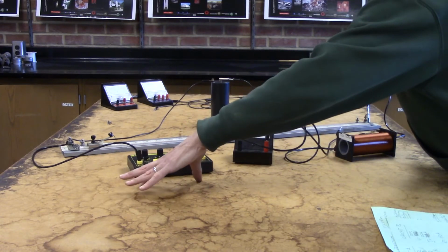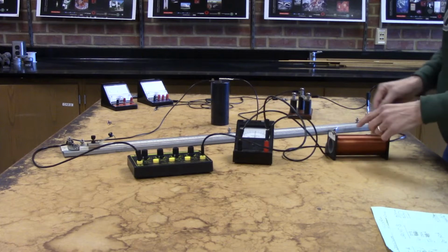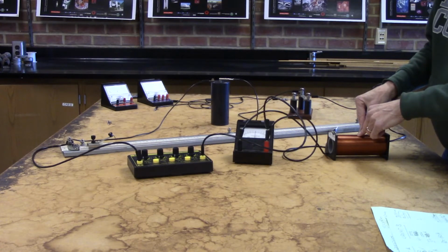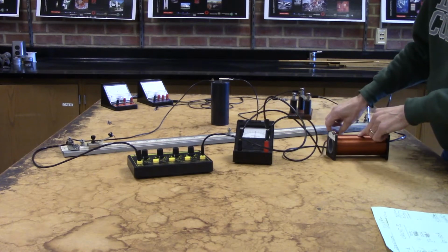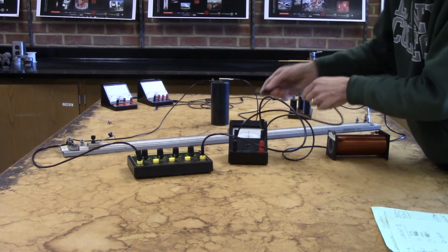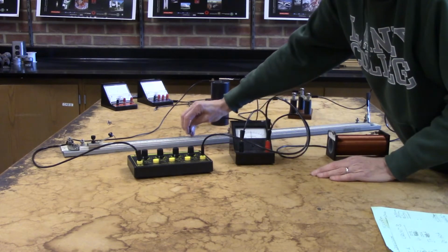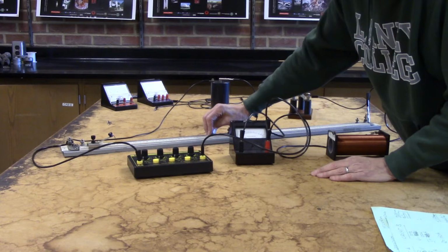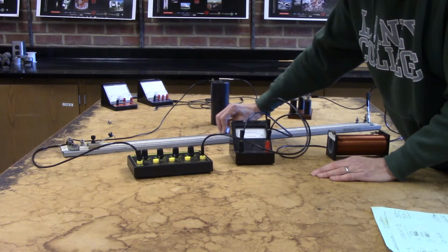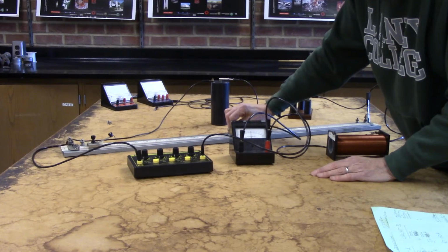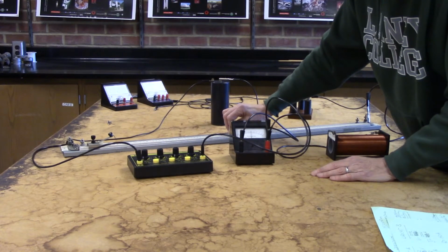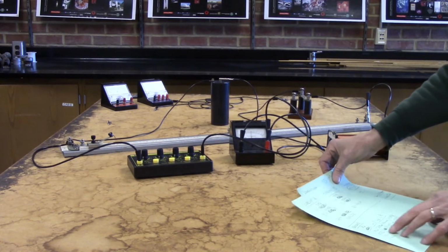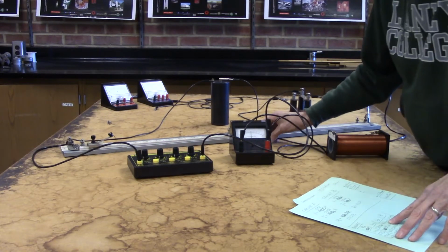I'm sorry, resistor 1, and then here is resistor X. So it's the resistor wire coil again, and then I'm running this through a galvanometer, and what you can see is that when I make a connection with R2 and R3, this galvanometer is showing that we're not balanced yet. So I'm moving this back and forth, and I don't know if you can see this, but the scale zeroes out about right here. So it's zeroing out at about 46.1 centimeters is where I found that.